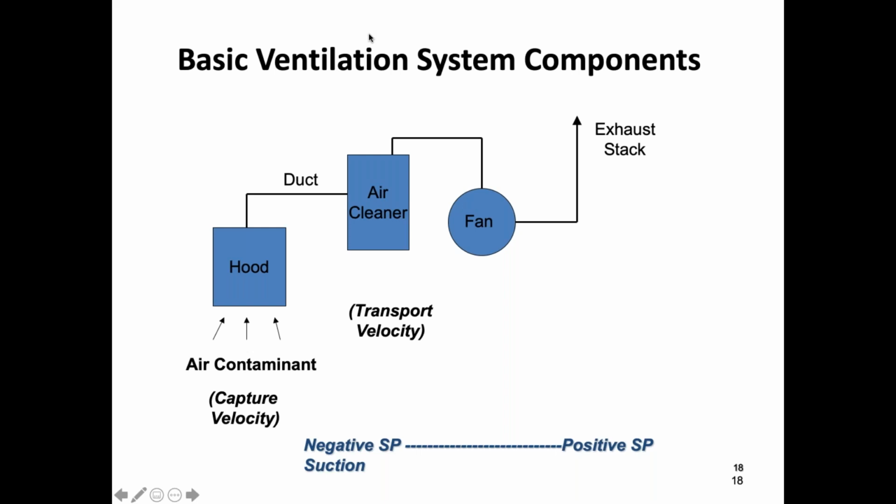As a matter of fact, most lab hoods have markings on them, where the person that calibrated that hood tells you that when the sash, the plexiglass screen, is down at this level, you're getting 100 feet per minute of air velocity being pulled in through that opening. Another marking that's lower might say 200 feet per minute. So you know what level you need to protect yourself, depending on how dangerous the material is that you have inside the hood, right?